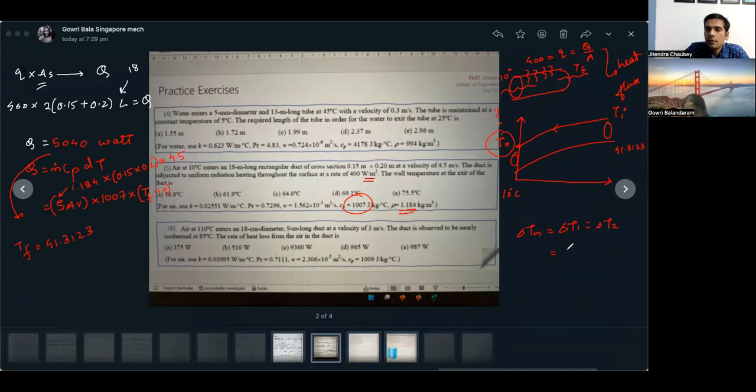You can say I want T0, and it will be T0 minus 10 degrees Celsius. So this is delta T mean itself. Since this is delta T mean itself, we can use the formula Q is equal to H A delta T mean. Is H given, or do we need to calculate it? We need to calculate H also.